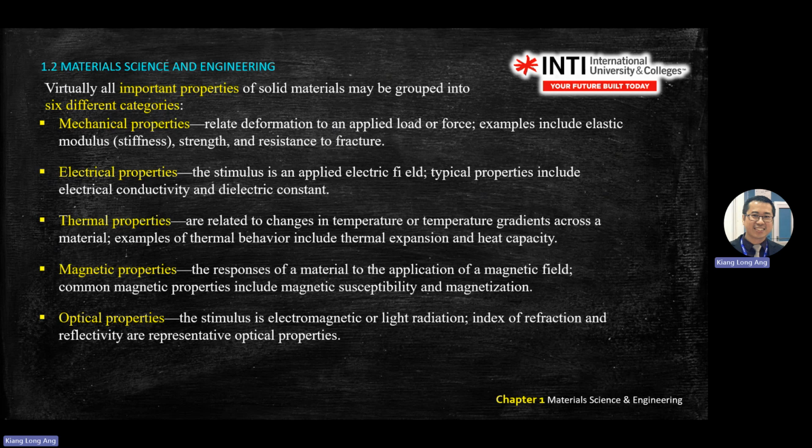Anything that is related to force or pressure. Load can be the word load. It can be force in Newton, or it can be pressure in Pascal or Newton over meter squared. Okay, so you need to be careful on the question. Sometimes the question just uses the word loading, and then you read the question, whether the question asks you to answer in force or in pressure.